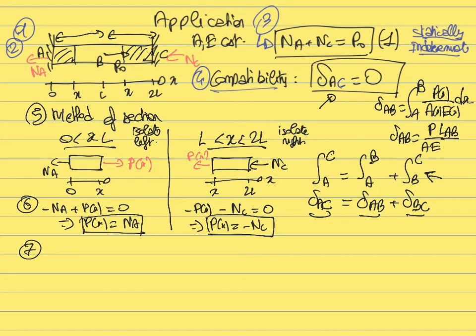So that's always something that you can use even if the load, for example, is not constant throughout the entire beam, but if it's constant by pieces over different regions, then you can apply this simplified equation. The only case where you would really need to solve explicitly the integral is when you have either the load or the area of the cross section or the Young's modulus that is really a continuous function of x. So let's do this.